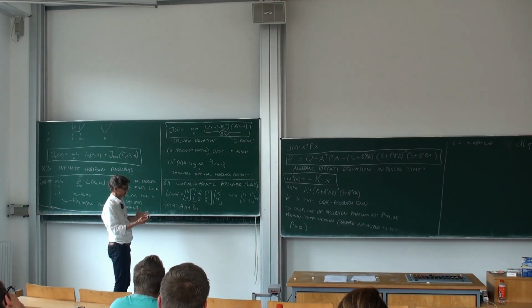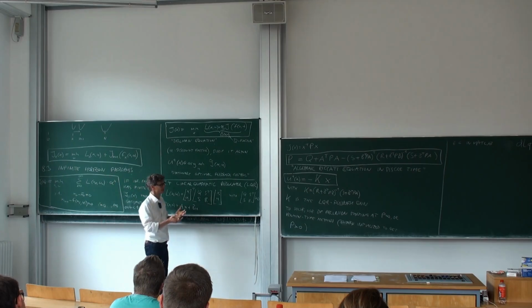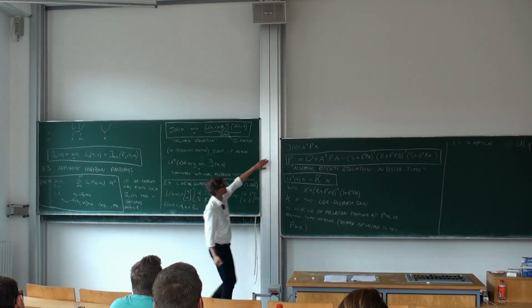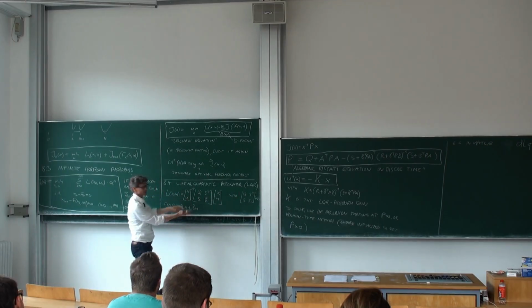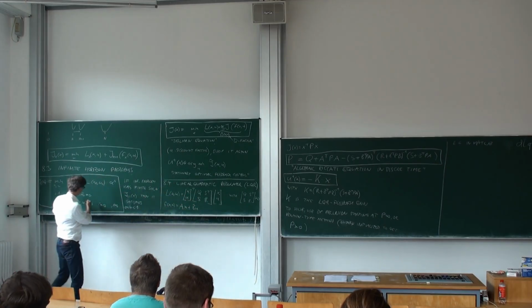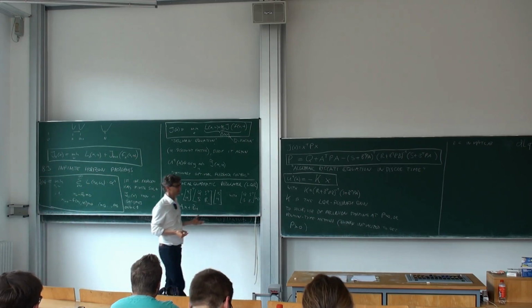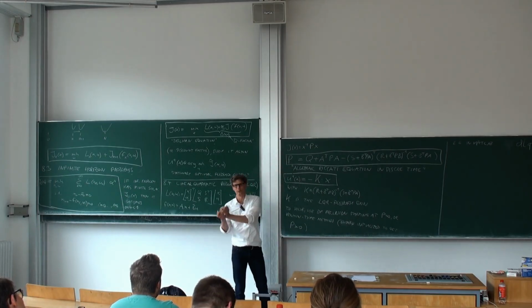So you can easily incorporate this concept of state constraints and control constraints into the definition of the Bellman equation. But unfortunately, it's not possible to represent all this with just one quadratic function of the form J(x) equals x transpose P x, even when your cost was quadratic plus some constraints. If you have a quadratic cost and some constraints, like even linear inequalities, which would lead us to a QP, you would not have a nice recursion for these cost-to-go functions.